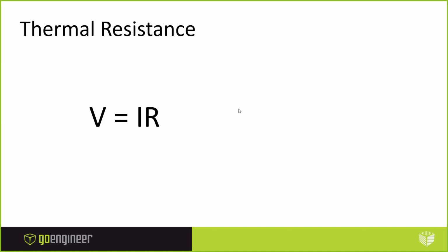Now, the basic principles behind some of the calculations we're doing inside of any thermal analysis tool, we're going to talk about this concept called thermal resistance in a bit more detail. I alluded to it a little earlier on in this presentation when I used thermal grease as one example, but thermal resistance can apply across the board to a lot of components in your model, as well as the thermal resistance to the air. So it's important that we just talk about this briefly to really clarify what we mean by thermal resistance.